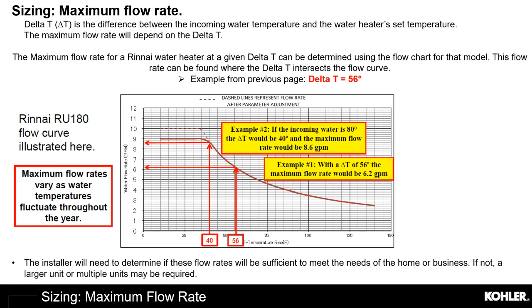Now, this is Atlanta. Remember when I said Wisconsin, it's probably about 20 degrees cooler. That means we're going to get less GPM total flow out of each unit. And that's not based on the unit issue, that's based on inlet groundwater temperature. So another example, if we were having inlet groundwater temp, example number 2 at 80 degrees, maybe in a warmer climate, maybe the Caribbean area, Hawaii, some of those larger, nicer, warmer areas, or if you have tanks that are holding that 80-degree temperature, this is going to give you an opportunity to get up to 8.6 GPM.